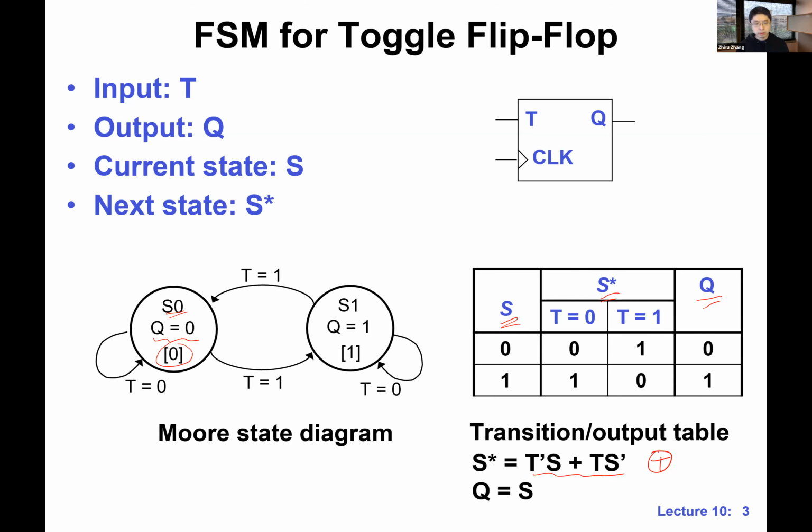Okay, all right, so this is the T flip-flop, right? And maybe real quick about prelim, right? There's actually a prelim question where I ask you guys to build a D flip-flop, right? Out of TFF, right? It's actually very much symmetric to how we build T flip-flop out of DFF. So all we need to do is to add the XOR, right? Over here on the input side. And we connect Q over here, and then this is D.